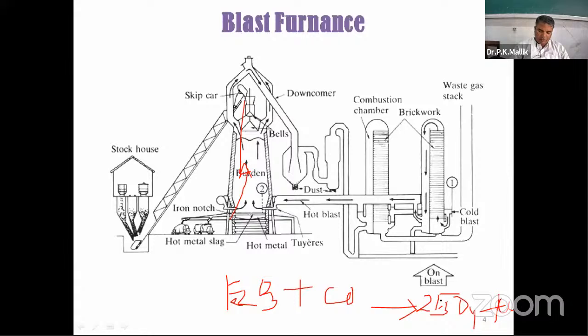The final reduction is accomplished down in the cohesive zone, where high temperatures and highly reducing conditions result in reduction of wustite, or iron oxides, to iron. Impurities such as silica, sulfur, alumina, and magnesium present in the original pellets associate with the lime and are removed as the molten slag. So the final reduction of the iron oxide takes place by mass transfer mechanisms.